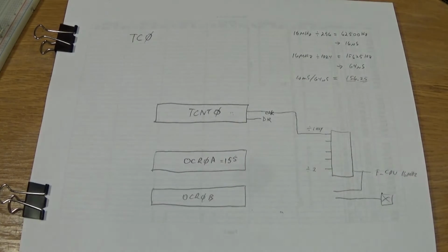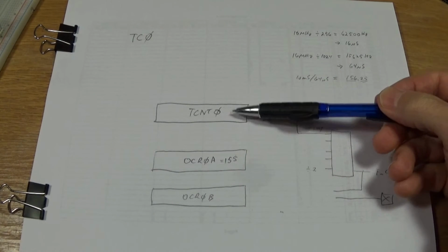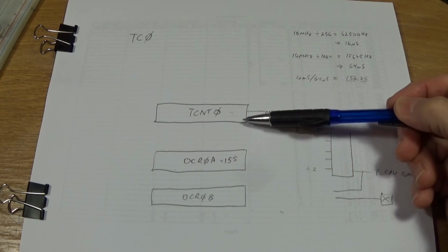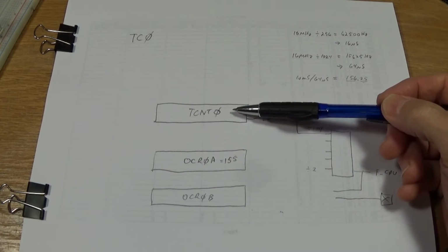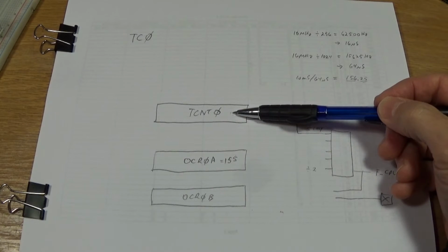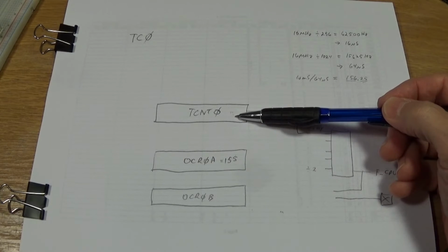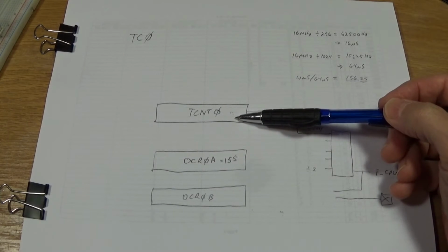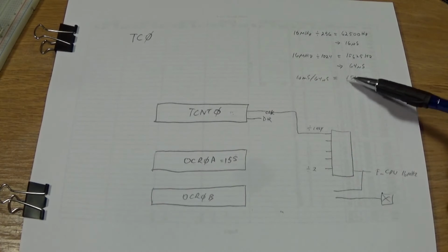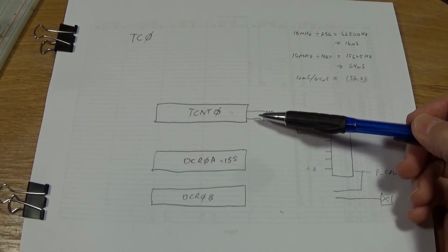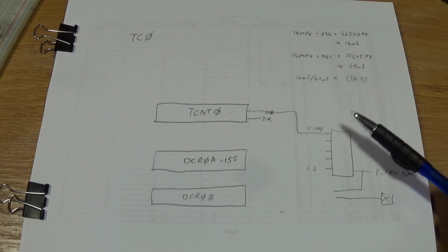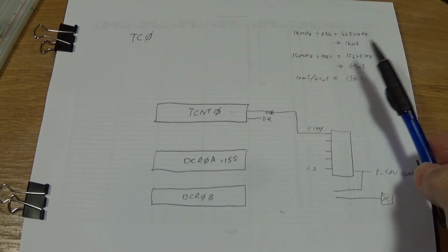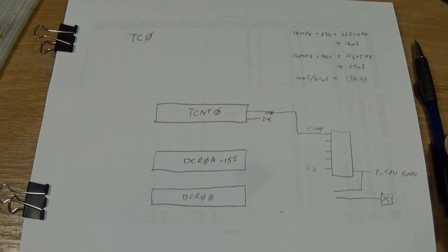like that. And what happens is that this clock will count up from 0 to 155, and when it matches, it creates that interrupt and then resets this register back to 0. So this register doesn't go as high as 255, which is all ones in there. It only goes up to 155. So it counts from 0 to 155, which is 156 counts. That's where the minus 1 comes from. And so that will give me approximately 10 milliseconds between each interrupt. So that's how we are going to program this timer counter in order to give us a 10 millisecond interrupt.